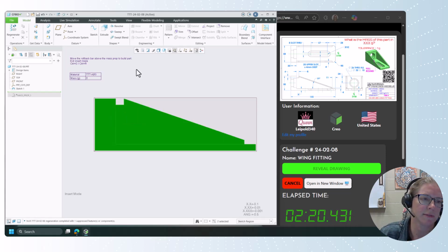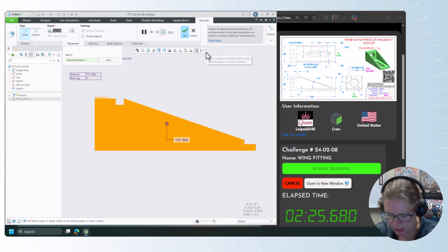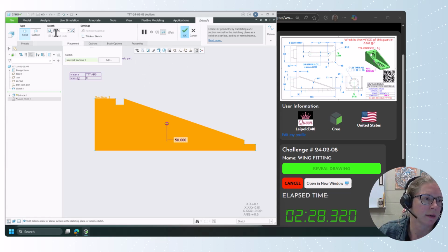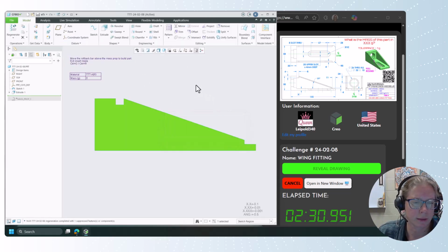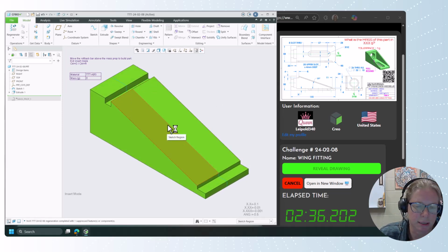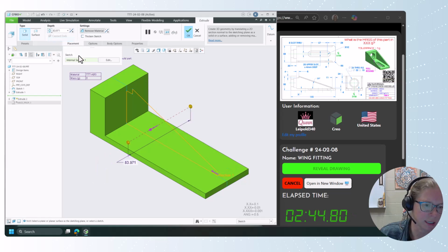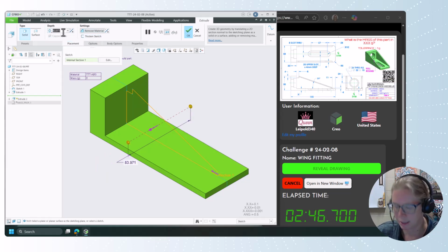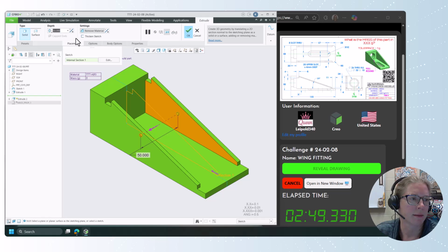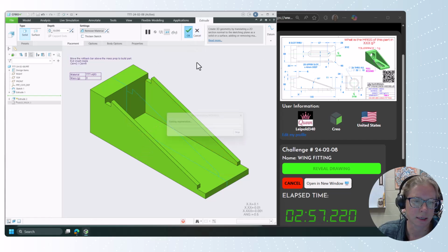We can select both of these faces and extrude that. That one's going to be the depth of 58. That value's in your top view. We do want this to be symmetric. All right, so I want to get this sketch region here, but I'm having a hard, well, hey, there we go. That's the one I want to extrude. We're going to make that symmetric, and we're removing material. And the depth of this is going to be 50. And that number comes from the 58 minus 4 here, and the fact that it's symmetric, so 4 on the back side, so 50 is our depth.